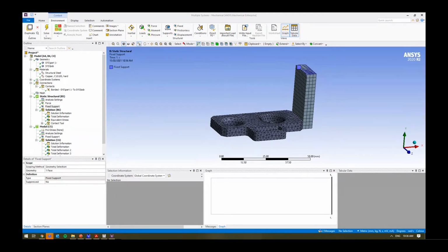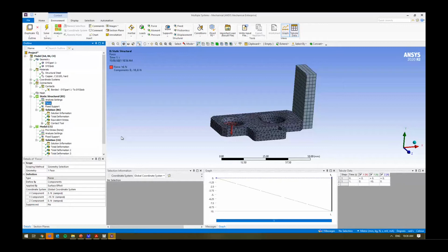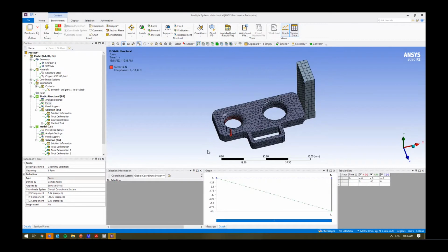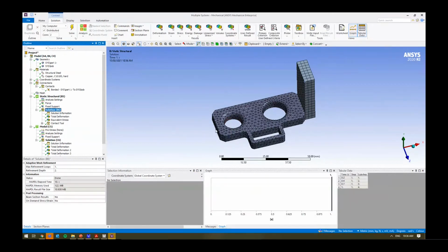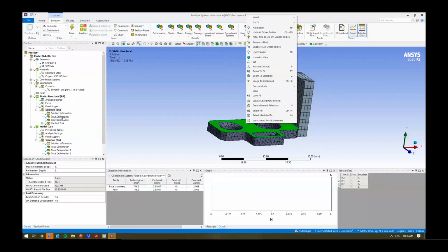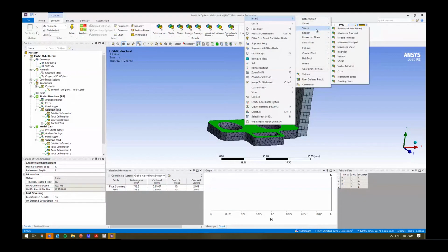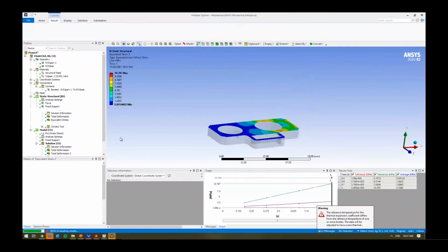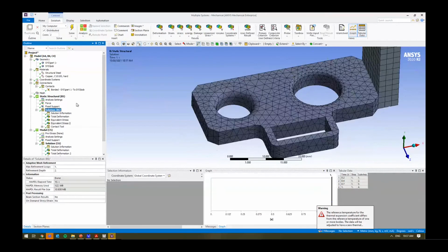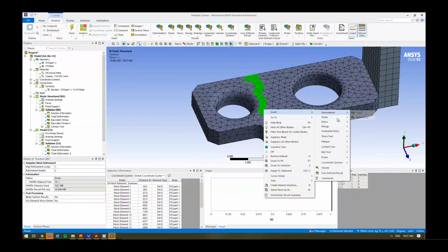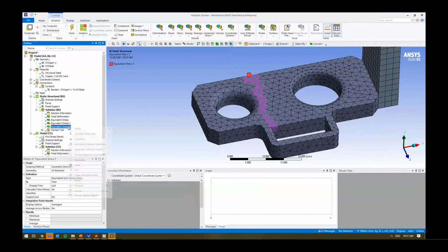Different dimensions of the object. I'm not exactly sure what you mean. If you want to investigate stresses around a specific spot, one of the things you can do is apply stress analysis to a specific surface. We'll talk about this in more detail tomorrow. So you can select that surface, look at the stress, and pick up what it might actually be. Another way is that you can pick specific elements and then display the stress on those elements, right?